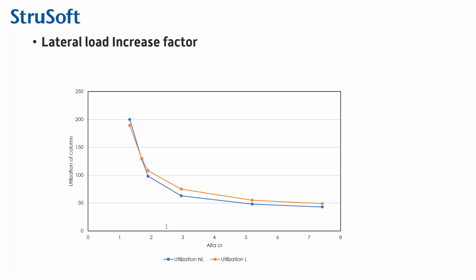If you have a really stiff connection and the bolts are really tight, then you increase your beam loading by all those imperfections, and that's why those semi-rigid connections should be avoided, because you don't want to go there. But if you have to, then you have to calculate them with this stiffness to get the right result. So pinned is not always on the safe side.